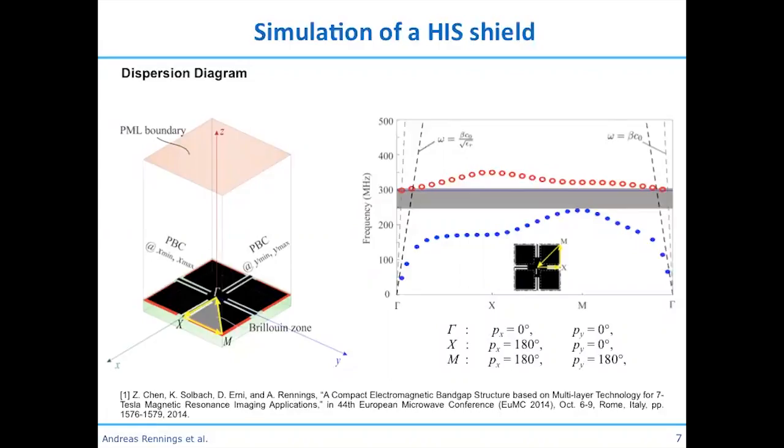So we specify here the phase shift along this cell. We may do it in a 2D manner for all values in that direction and in that direction, but this is highly redundant. We just calculate the resonance frequency inside this Brillouin zone.